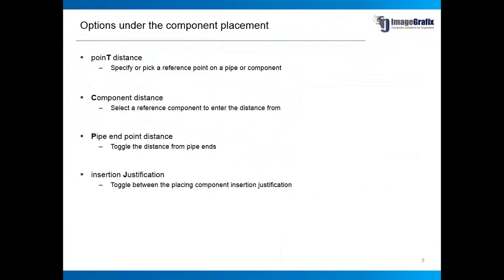Now in the next slide, the same thing I have discussed now: the point distance, to specify or pick a reference point on a pipe or component to place the component which you want to place on your screen. That is the first option, that is the point distance.